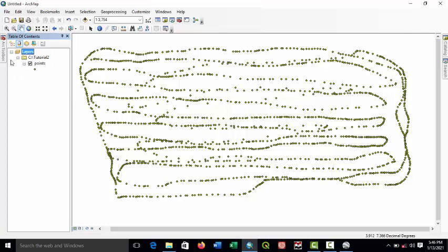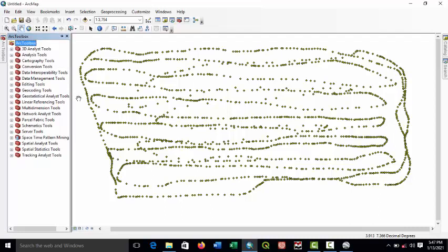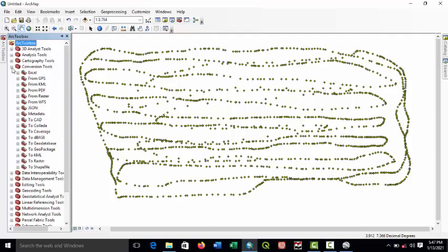Now the next thing you do is that you convert this from Topo to Raster. You use conversion from Topo to Raster, because we cannot create the contour like this. We have to convert it to a raster. Then from a raster, you can now create your contour. So the next thing is just convert to raster. So this is it, conversion to